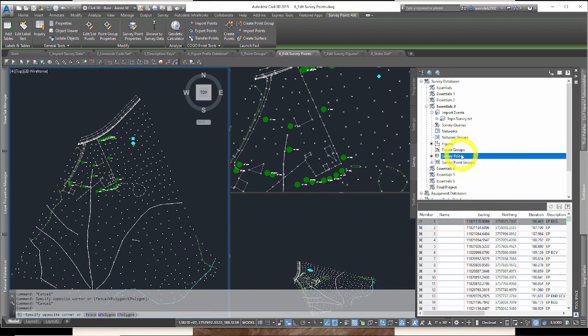A lot of companies like my own and others will keep this raw, sacred, untouched and unedited original data in a different program sometimes, like Trimble Business Center or Leica Geo programs. Sometimes it's done in Civil 3D in the survey database, but it is important somewhere in your chain of events from your raw data to have at least the original points in their pure form that came from the field.